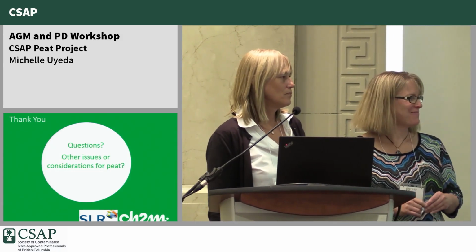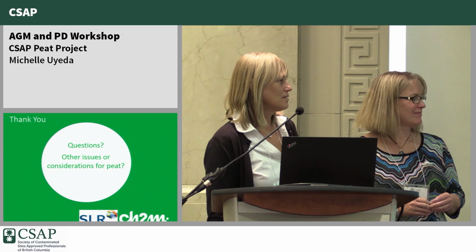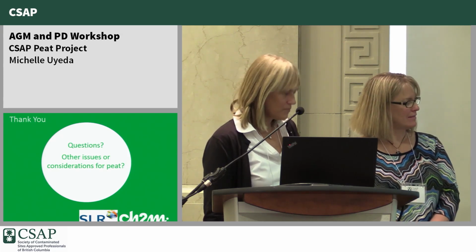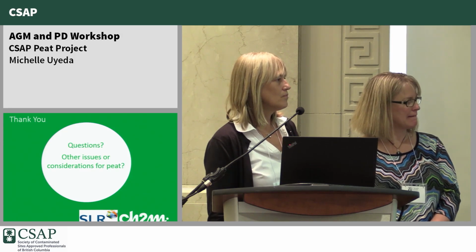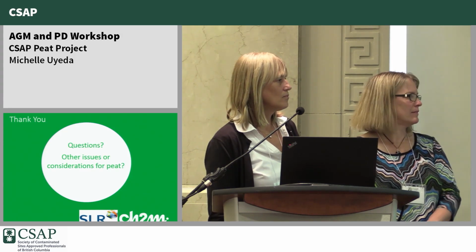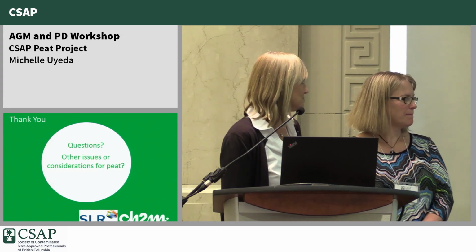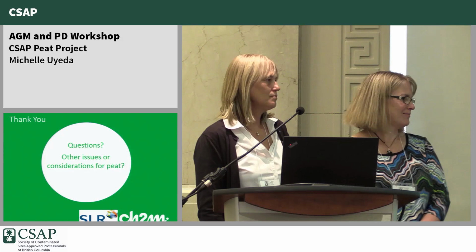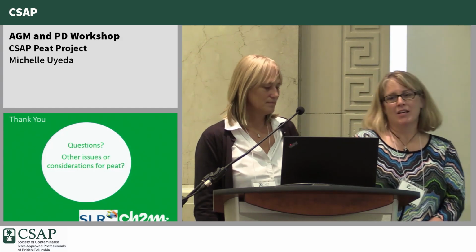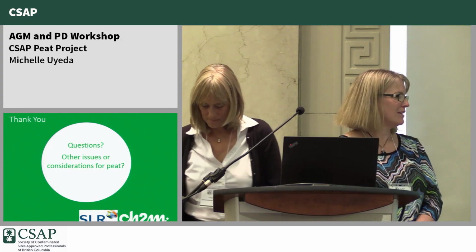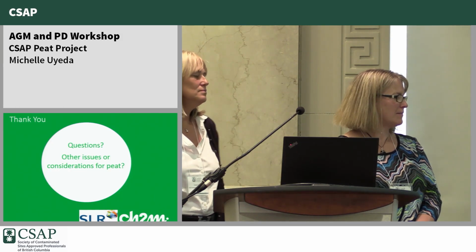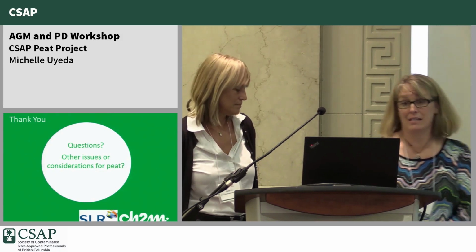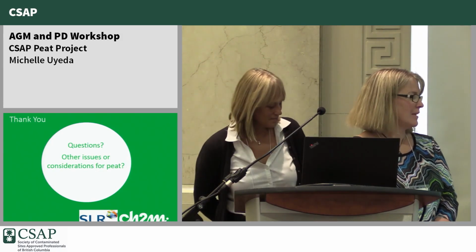Hi, Michelle. Thanks for the presentation. I was looking at a remote mountainside where I'm not sure if it was peat, but I think it was organics. And I'm curious about your particular reference to the wet weight concentrations. The ministry standards are all based on dry weight, right? Yes. So we can't really use wet weight concentrations. And I was just comparing the 2 methods of calculations. The numbers vary hugely. They do, yeah. Right? 5 to 10,000 micrograms per gram, right?